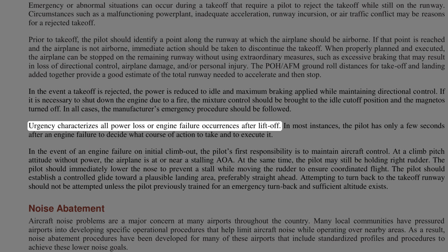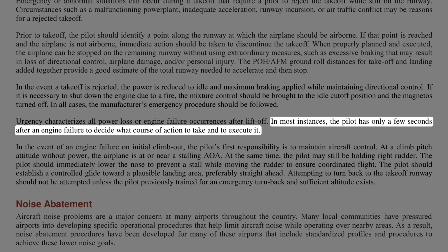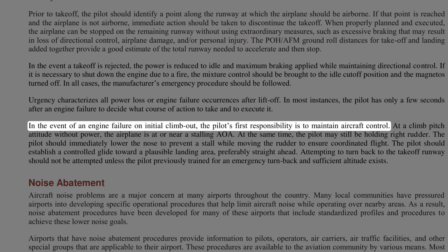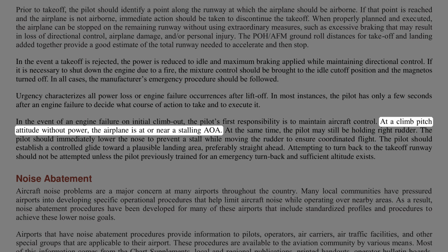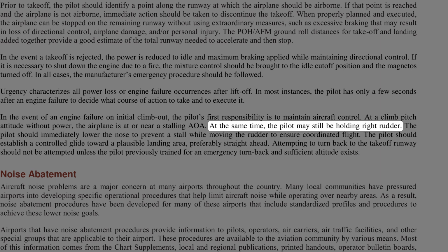Urgency characterizes all power loss or engine failure occurrences after liftoff. In most instances, the pilot has only a few seconds after an engine failure to decide what course of action to take and to execute it. In the event of an engine failure on initial climb out, the pilot's first responsibility is to maintain aircraft control. At a climb pitch attitude without power, the airplane is at or near a stalling AOA. At the same time, the pilot may still be holding right rudder.